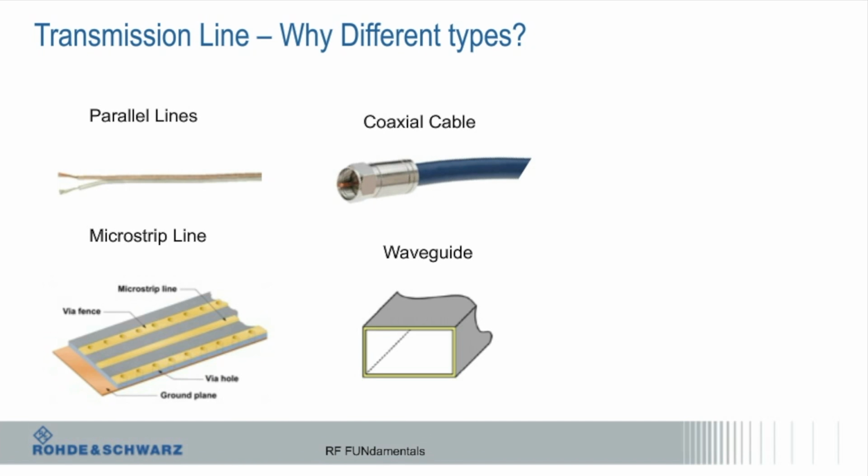Okay, so anyways, microstrip line is a transmission line on a board, and there are different variants of that. That's a single transmission line by itself, but then you can also have what's called a coplanar waveguide, which is a similar thing where the ground planes are more closely defined to maintain that and reduce the fringing effects. Then you have waveguides, and this is typically much higher frequencies, usually 20, 30, 50, 70 gigahertz kind of thing.